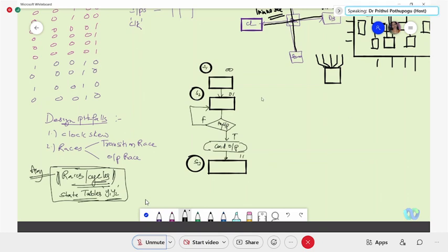Here, for each flip-flop to go from one state to another state, there is a need of change of the state variables to happen, or there is a need of an input change to make a transition between two stable states. Okay, and say if these inputs are happening at some interval where there is sufficient time for the outputs to be properly defined or evaluated, then the system is fault free.